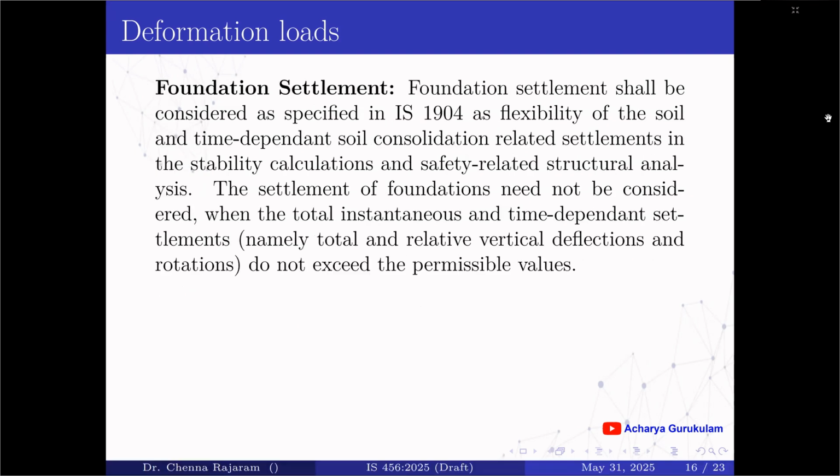The foundation settlements shall be considered as specified in IS 1904, as flexibility of the soil and time-dependent soil consolidation related settlements in the stability calculations and safety-related structural analysis. The settlement of foundations need not be considered when the total instantaneous and time-dependent settlements do not exceed the permissible values.